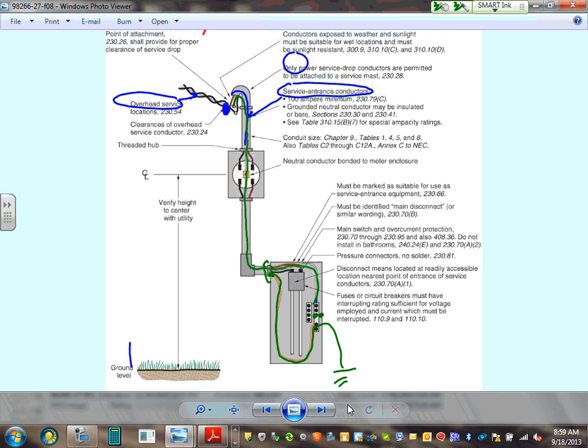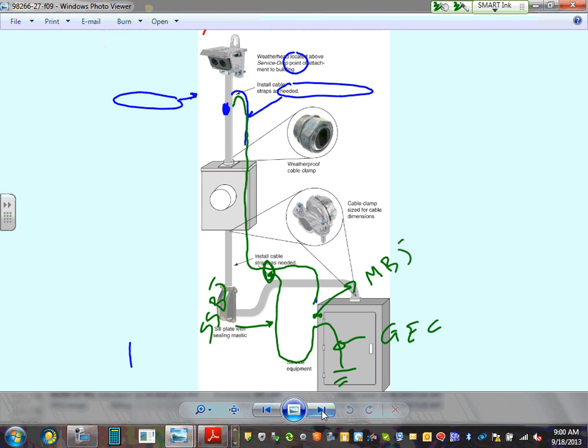And the pipe, can you guys see that pipe here? That's bringing the power in. If it's metallic, you bond it too. So a couple of names for this. This is called the grounding electrode conductor. The bonding here, this is called the main bonding jumper, when you bond the neutral to the frame of that box. This wire is called the supply side bonding jumper. So important, because based on the name, you'll be sizing them. Again, guys, you will hear a lot about this as we move forward in the commercial. There are a lot of rules and regulations when it comes to it, so be aware of that.